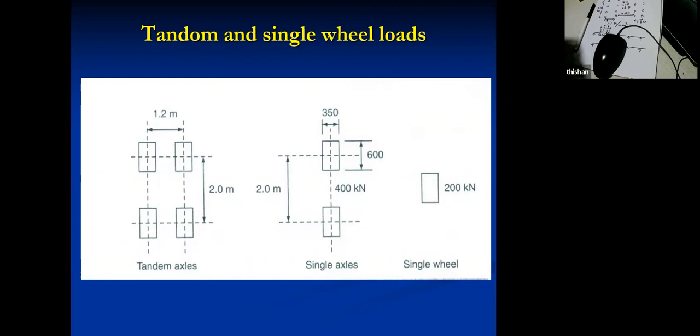So because of that, these days we always get the help of computer software like SAP 2000, CSI Bridge or MIDAS, and create a grillage and then apply the loads on the grillage, and then we try to get the maximum bending moments and shear forces. If you are not familiar with grillages, just read a book or type grillage analysis on the internet, and you can get enough videos and other information. And if you can get hold of software like SAP 2000, you can easily create a grillage in a few minutes, then apply the loads and see what's going on.